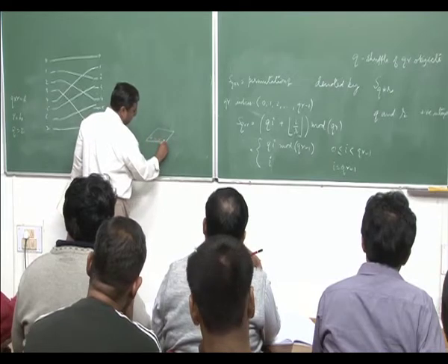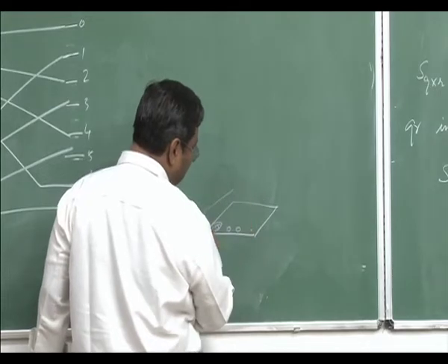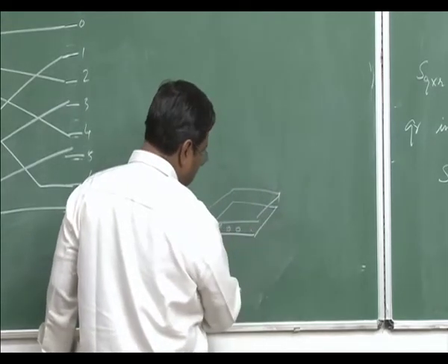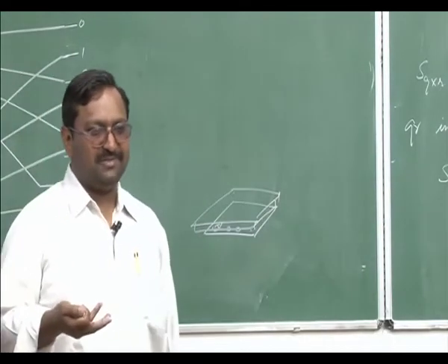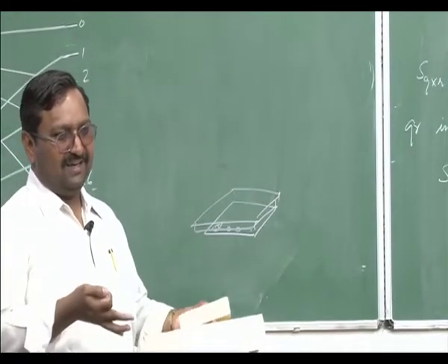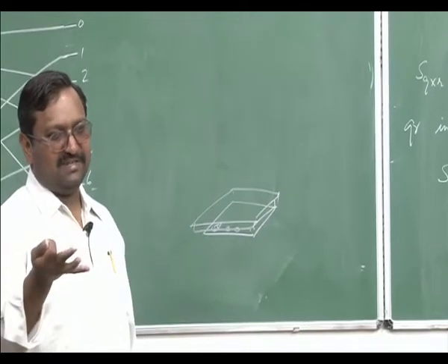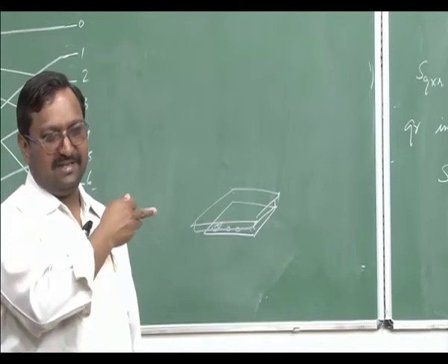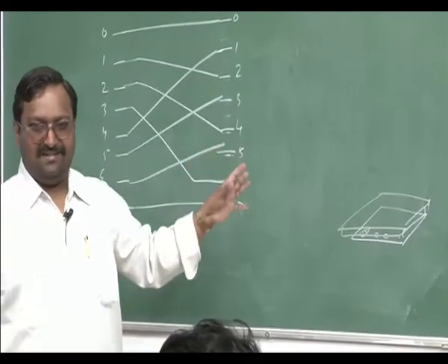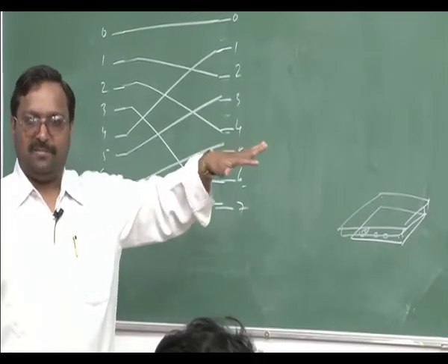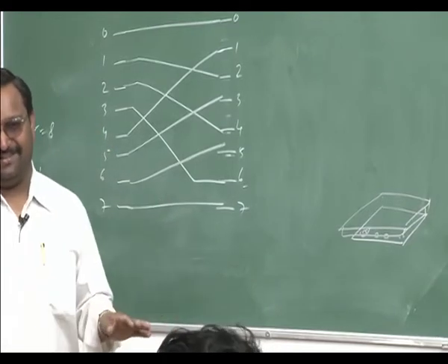All optical implementations will be something like this. You will have transmitters here. Each one is a processor, it will connect 2 inputs. On top of this, you will actually have a slab, which is a holographic thing. Computational holography actually is used. You create a phase grating technically, depending on what interconnection pattern is required. But remember, it is a 2-dimensional thing, it is not 1-dimensional. Here I am actually drawing 1-dimensional. So, 2-dimensional also can be done in the same fashion, but I am not moving to the 2-dimensional thing here.